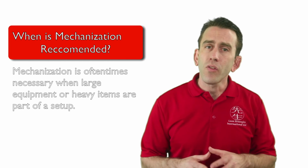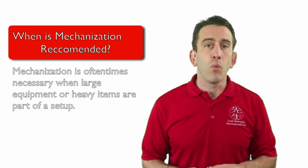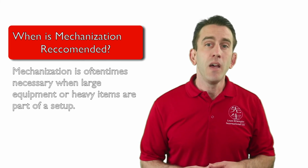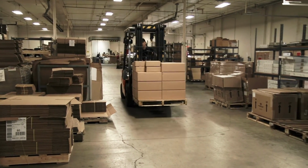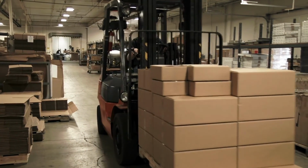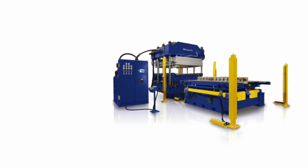With these two reasons in mind, mechanization is oftentimes necessary when large equipment or heavy items are part of a setup. Some practical techniques that can be used are using forklifts to move heavy items and insert tooling, tightening and loosening items, and use of moving bolsters.